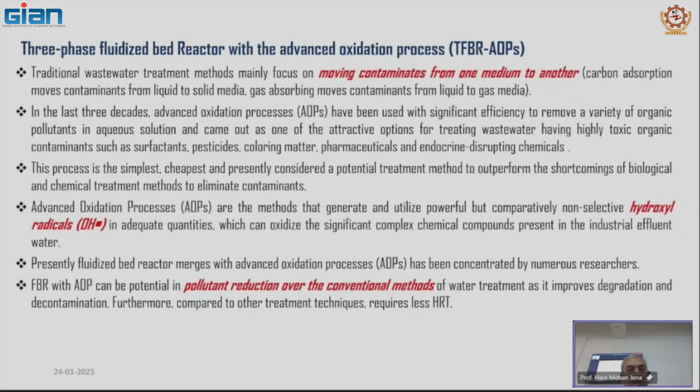This process is the simplest, cheapest, and presently considered a potential treatment method to outperform the shortcomings of biological and chemical treatment methods to eliminate contaminants. Advanced oxidation processes are the methods that generate and utilize powerful but completely non-selective hydroxyl radicals in adequate quantities, which can oxidize the significantly complex chemical compounds present in the industrial effluent water.